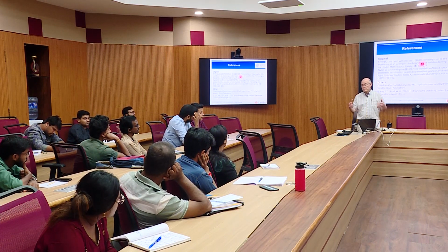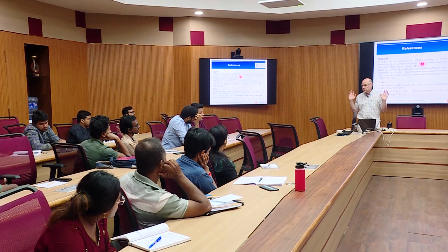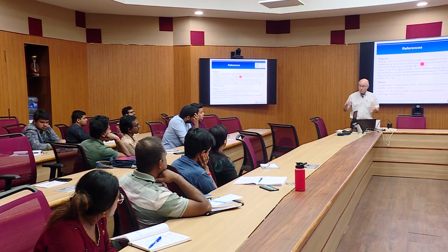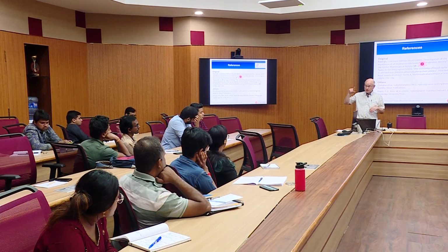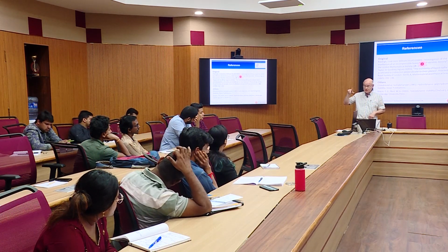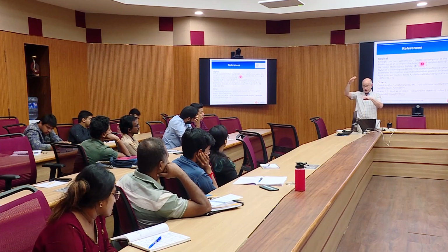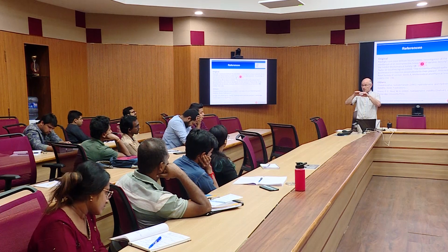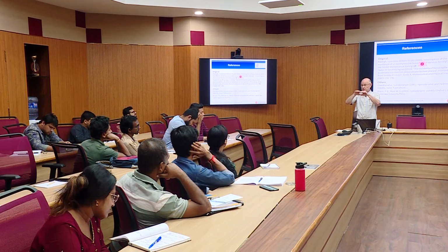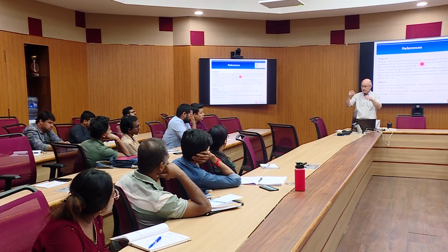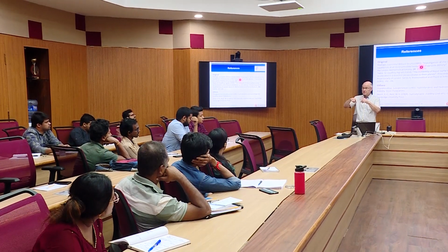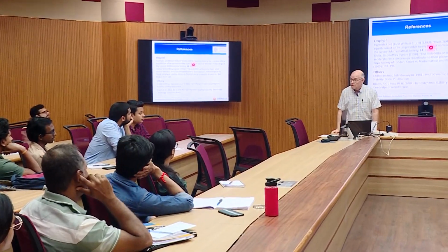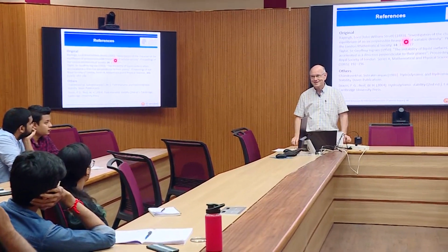Okay, you could call that a boundary condition, but if you go back to the Young-Laplace equation, it's a delta P. So if you change, let's say, one of the domains in pressure, all we're saying with the Young-Laplace equation is that if you go across a curved interface, the pressure changes. The absolute pressure doesn't play a role. I don't know if I understood the question.